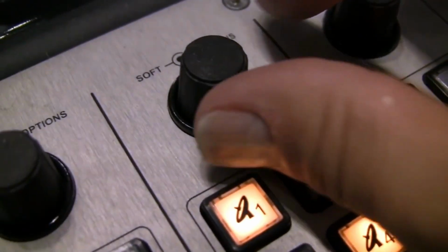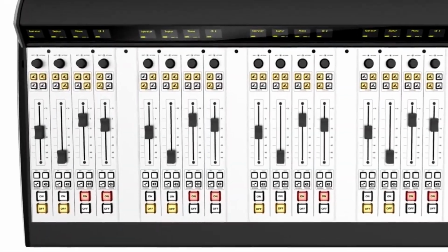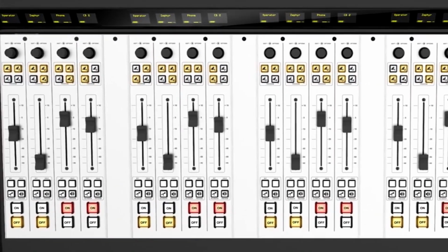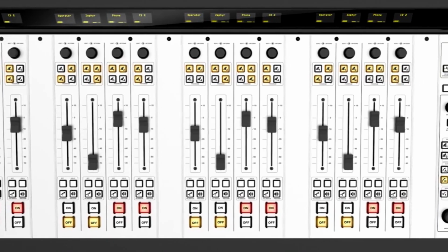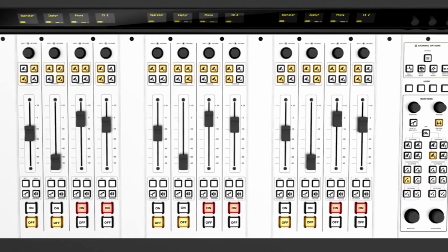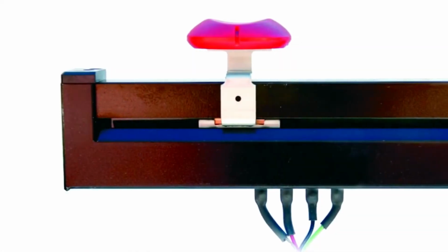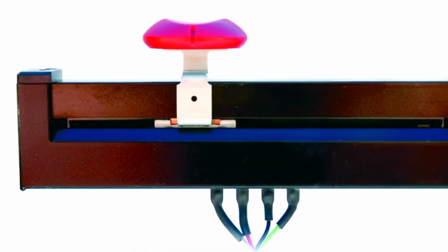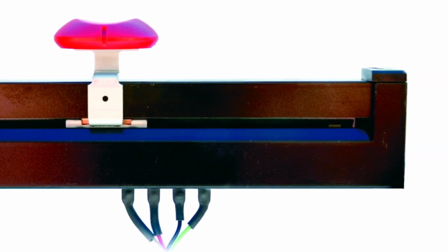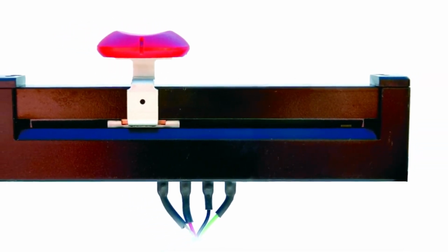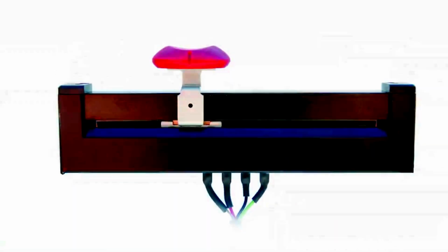No wipers to wear out on our rotary encoders. They're all optical. Some of the most important parts of any console are the faders. One of the reasons faders fail is from dirt, grime, and of course liquid that falls through the slots in the modules. Fusion's faders are special, premium, conductive plastic faders that actuate from the side, not the top. That way, dirt that falls through the surface slots falls past the faders, not into them. They stay smooth and silky nearly forever.